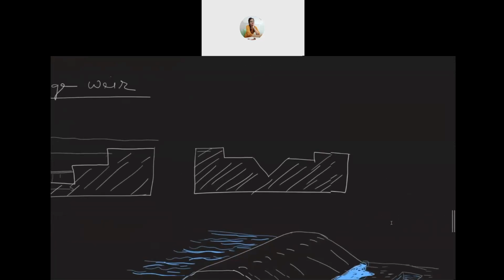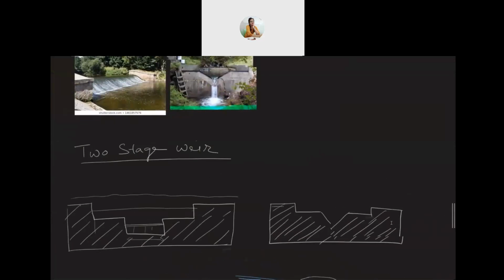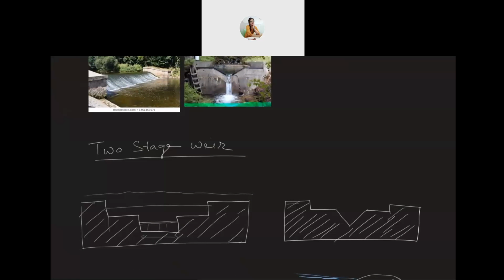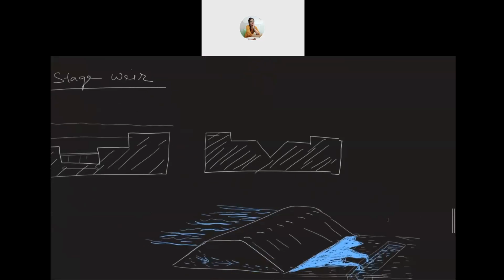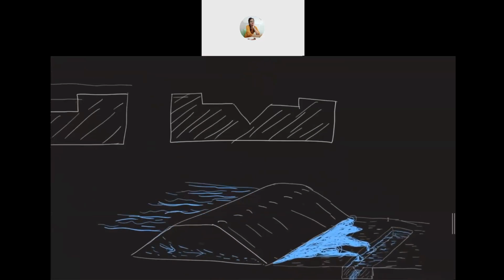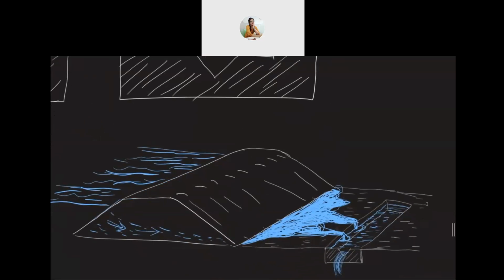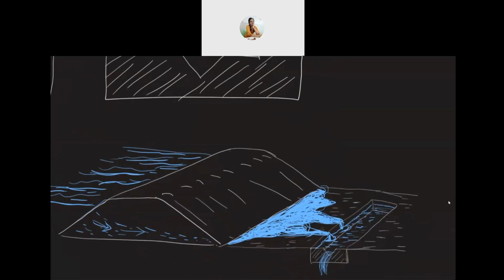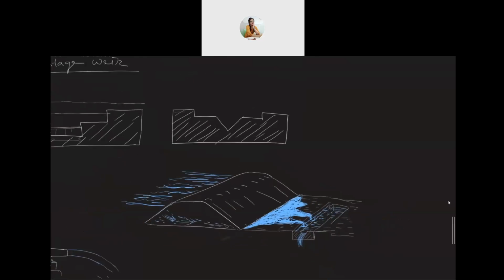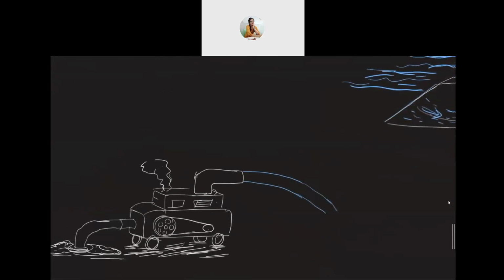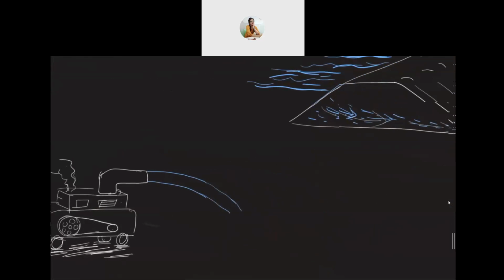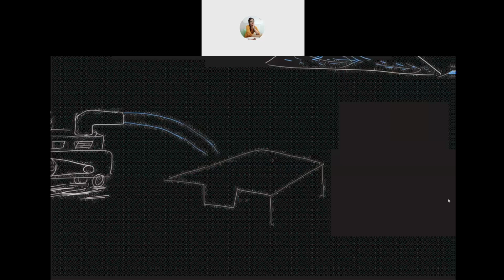So these notches and weirs are flow measuring devices. They are used in different situations, sometimes to measure discharge in rivers, sometimes in streams, sometimes when you have leakage through some kind of embankment, an earthen embankment, suppose, sometimes when there is pumping but you cannot find out the discharge rate of the pump. So in that case, you provide some kind of tank like this, and you collect the water, and in the tank, you provide some kind of notch.